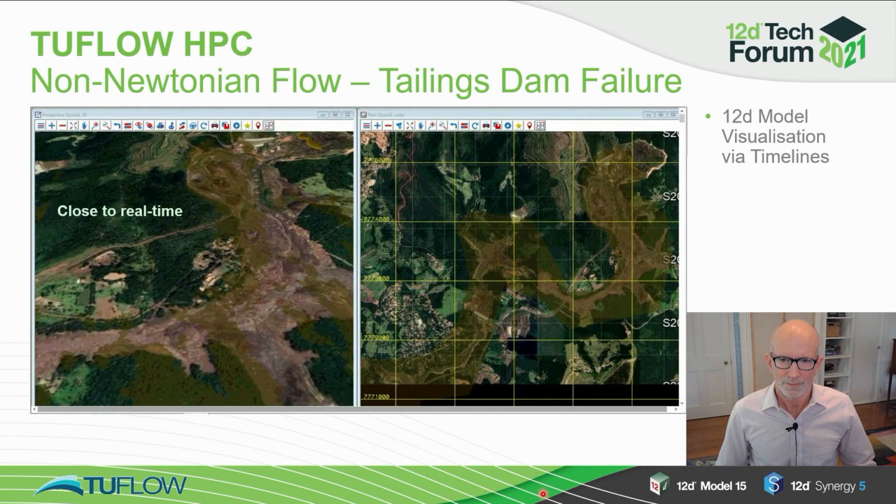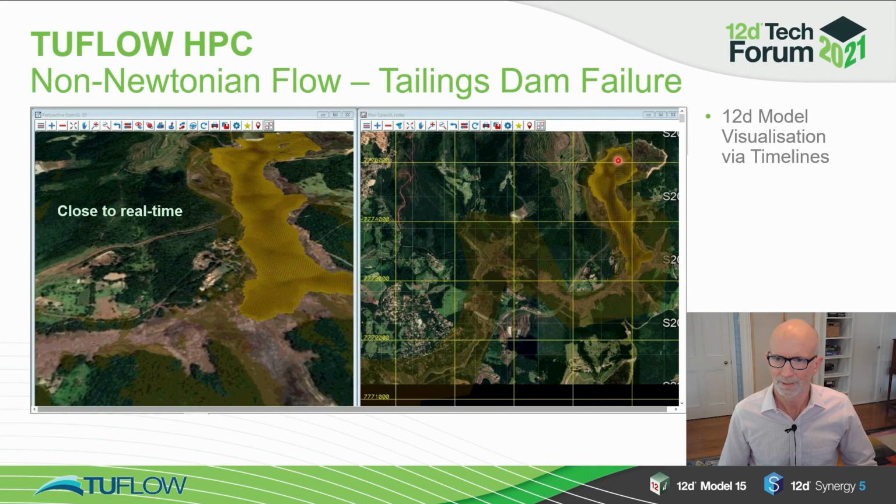So you can now simulate those in TUFLOW. You do need quite a bit of experience or knowledge about what parameters to apply, because every non-Newtonian fluid is different to another non-Newtonian fluid. What you see on the left here is the dam coming down. This is actually close to real time that we're simulating. And on the right we have the plan view.